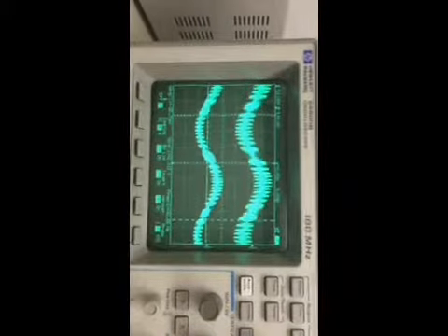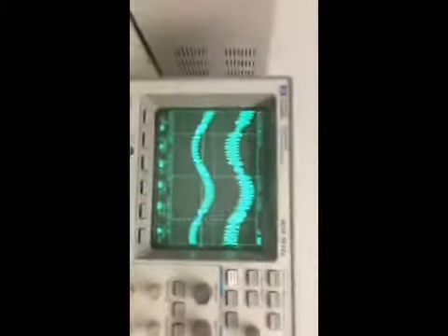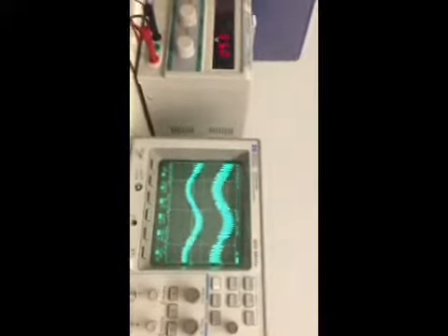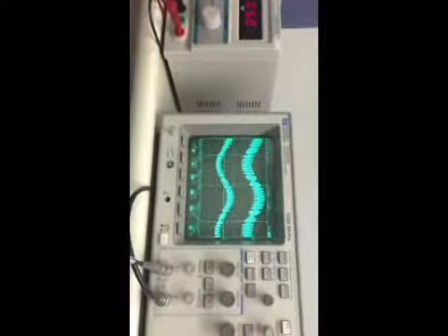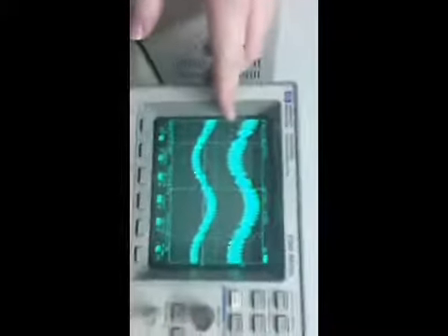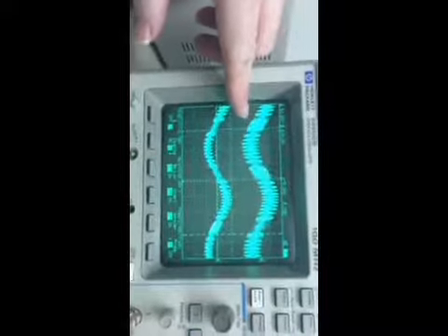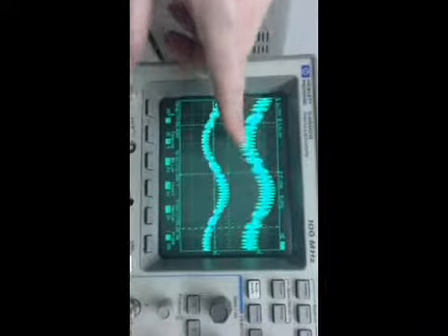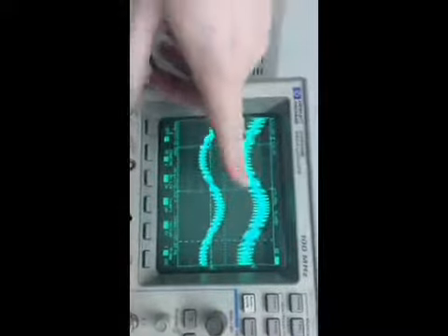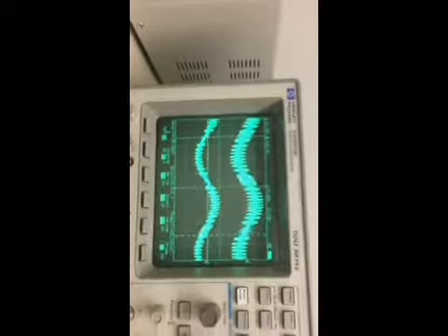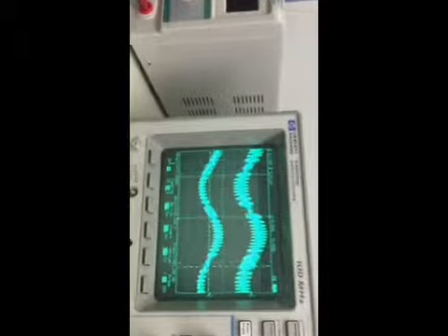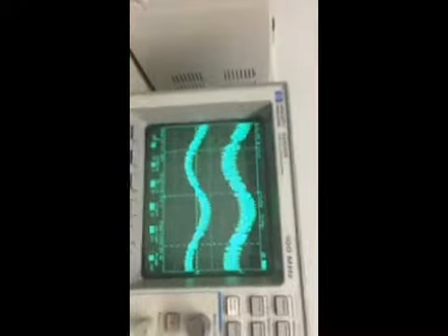The reason why we're using a different oscilloscope instead of the Tektronix oscilloscope is because we actually want to see the aliasing of the signal. So we had to downgrade our oscilloscope to be able to see the aliasing. The aliasing is realistically showing the difference in the 9960 signal as it's going over the frequency range. These nodes right here are showing the lower speed part of the signal as it's going between 9930 and 9990 hertz.